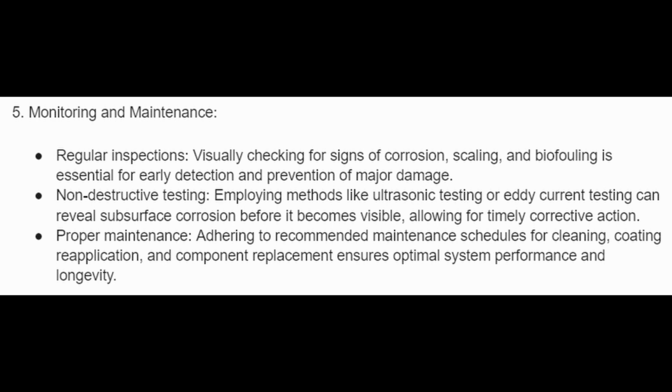5. Monitoring and maintenance. Regular inspections: visually checking for signs of corrosion, scaling and biofouling is essential for early detection and prevention of major damage.